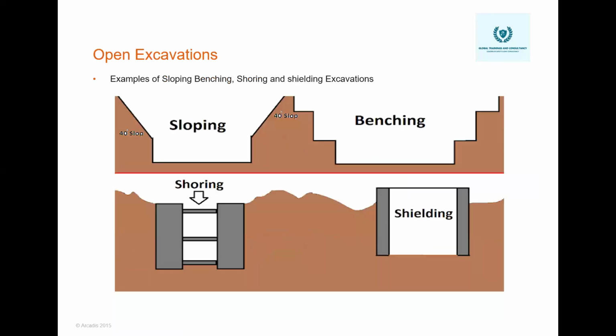So how do we protect excavation? We have to protect ourselves, people, equipment, machines, environments. And when we are doing excavation, we need to check that there is nothing underground. For example, we deploy an excavator to do the excavation. Before that, we need to check that there are no underground utilities.